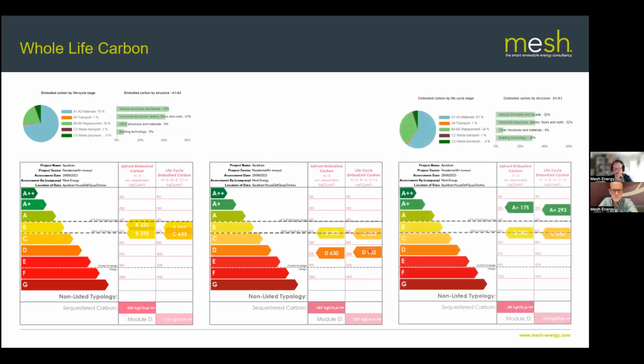When we compare that alongside the proposed design, you can see the sudden shift into building technology. So in here, we've got ground source heat pumps with horizontal collectors. There's a reasonable size solar array. It's not overly massive. It's probably twice the size of a typical detached house array, so about 8 kilowatts.